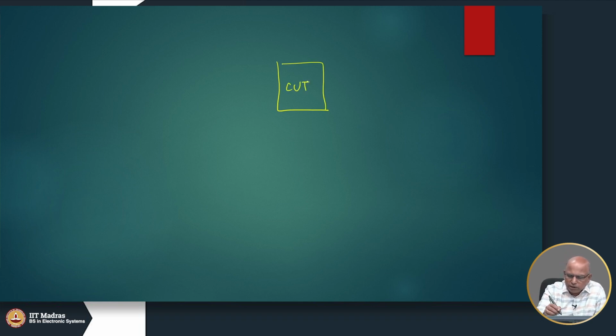And we want to apply random tests, so random patterns, because we do not have a way to do test pattern generation and bring deterministic patterns. Okay, we are applying random patterns, and random patterns actually tend to detect quite a bit of faults.